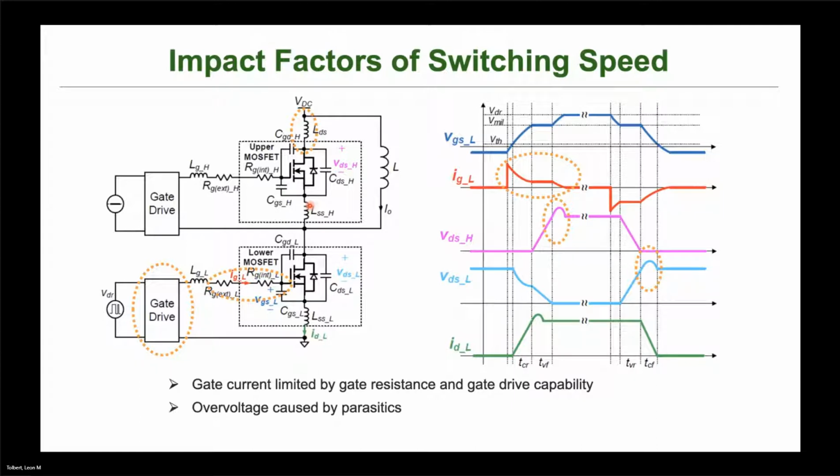That overvoltage is typically caused by parasitic inductance in the circuit and the current through that. And if that current change rate is too high, then again, we can end up with an overvoltage and damage our device. So much of the rest of the seminar is going to be talking about how we can improve the amount of current we can put in so we can turn it on more quickly, as well as when we turn it off, we don't want this large overshoot.